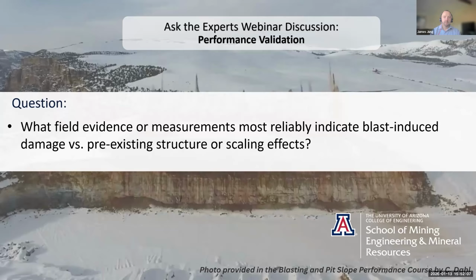A good blast supervisor knows how the various shots have been loaded, and they generally know if it's gone well or gone poorly. And so it's worth spending that time, because those are pieces of data too that you can pull into your inspection reports or logs or wherever you're keeping information. And again, the more you can do that, the better you're going to get at distinguishing when things have gone to plan and gone well, or not.